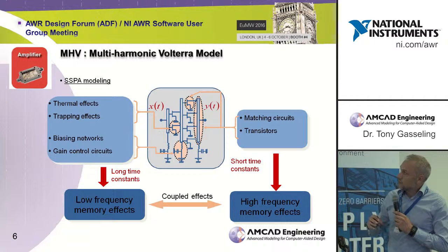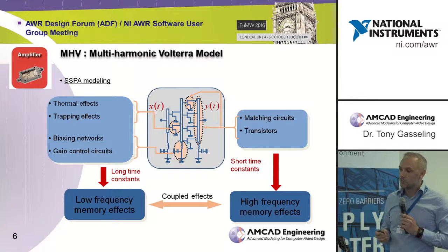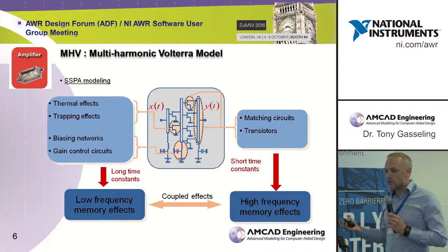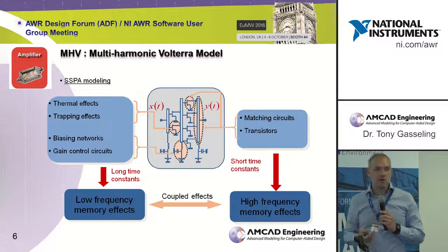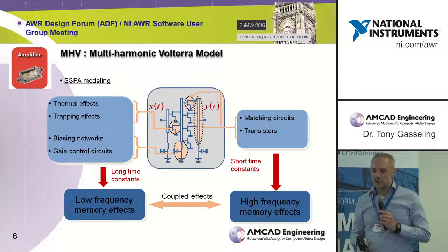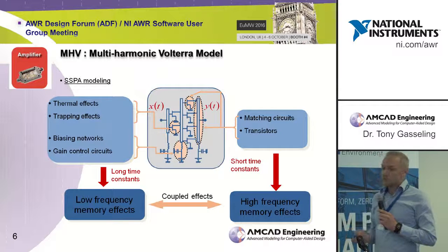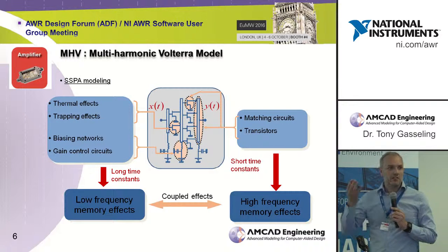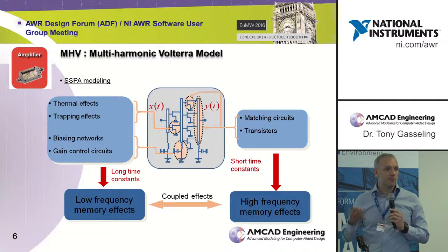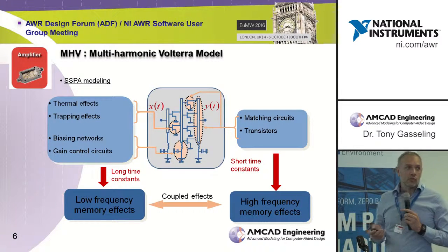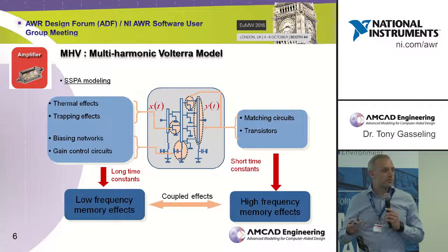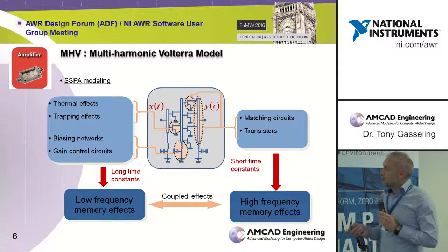On the other side, if you are at the peak output power, most of the consumed power is converted into useful RF power, so the temperature is lower. So when you are using a modulated signal, you are heating and cooling your amplifier dynamically, and this causes some long-term constants that could distort the output response.